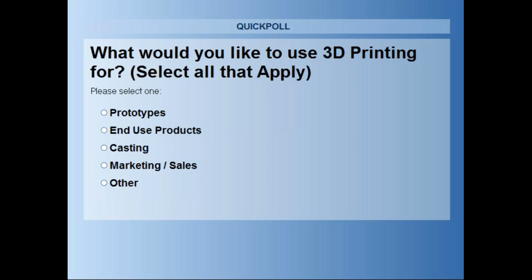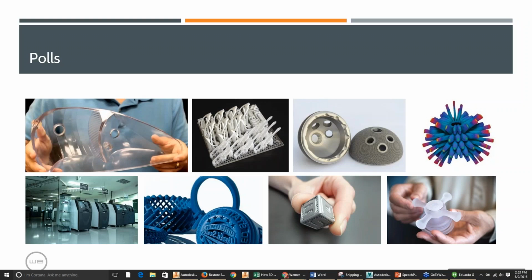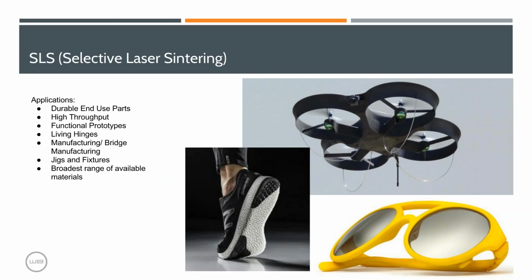So this stuff is actually really cool. The last two technologies I'm going to talk about are very, very impressive. So with these SLS printers, you can produce end-use parts. This is really, honestly, the main application for this type of printer. You want something that you can throw against the wall, run over with a car, beat up. The SLS is what you want to look at.